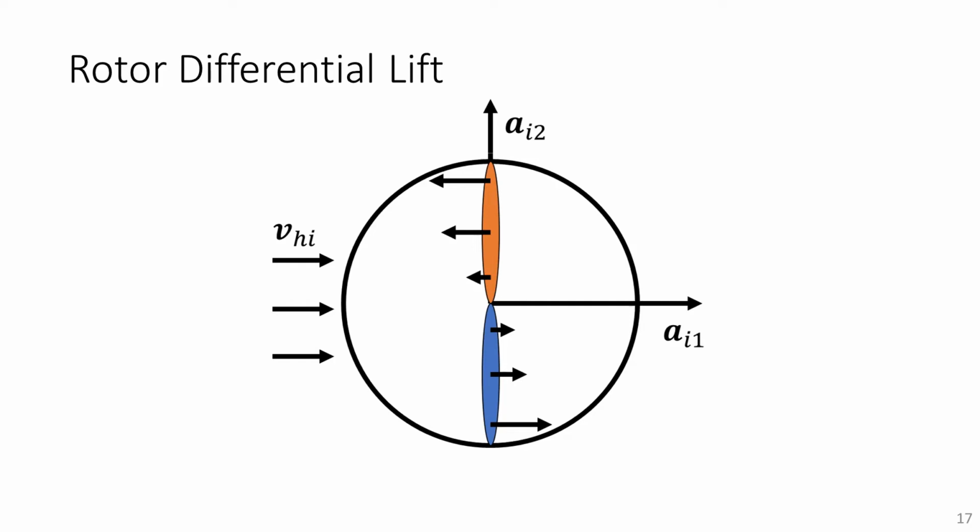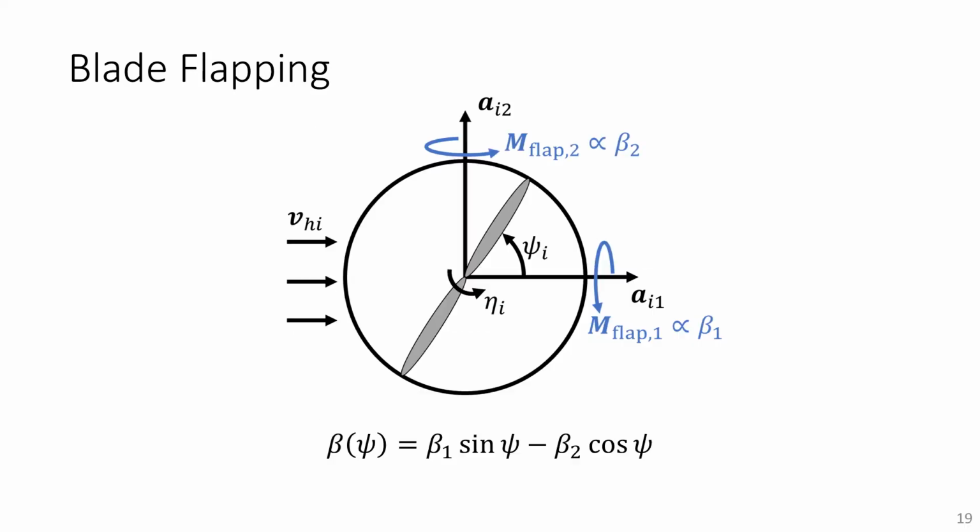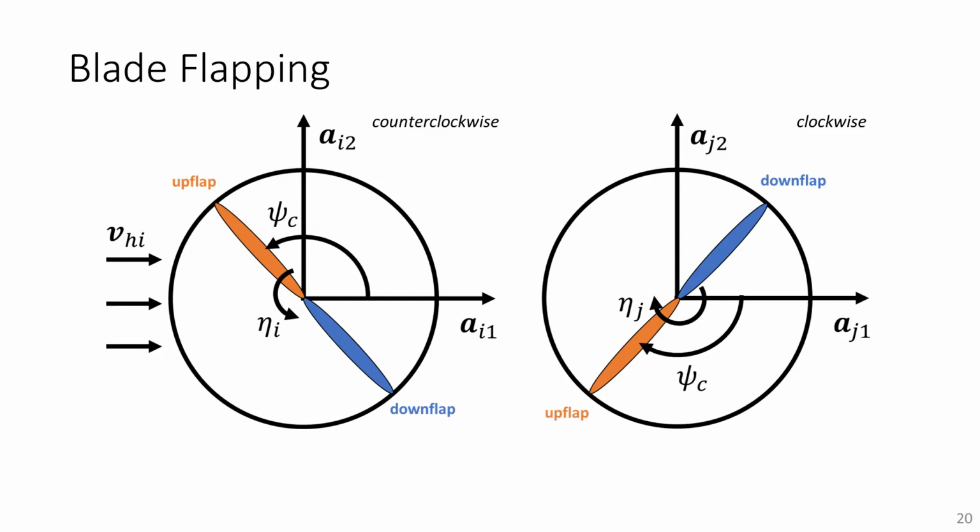This aerodynamic forcing causes the blades to flex up and down and exert a restoring moment on the hub, and that restoring moment is the true torque on the airframe. The second-order cantilever dynamics cause this reaction moment to be somewhat out of phase with aerodynamic excitation, and be neither aligned nor perpendicular to the flow.